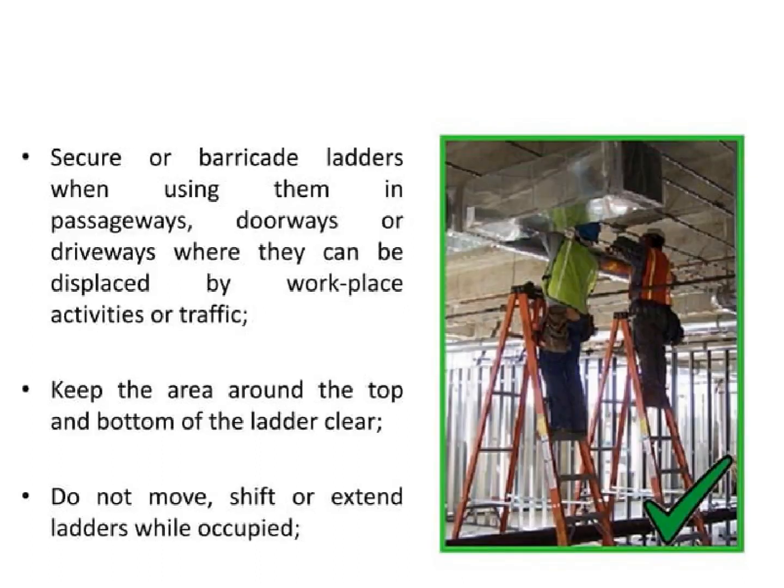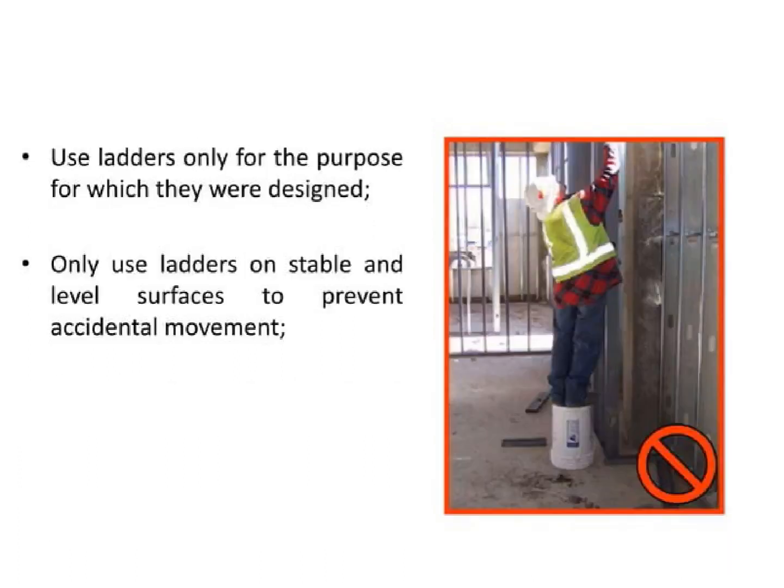When using ladders in doorways, passageways, or driveways, it is important to secure or barricade them to prevent displacement due to workplace activities or traffic. It is also important to keep the area around the top and bottom of the ladder clear, and never move, shift, or extend ladders while they are occupied. Ladders should only be used for the purpose they were designed for and should be placed on stable and level surfaces. Necessary safety precautions should be taken while using ladders to avoid any accidents.